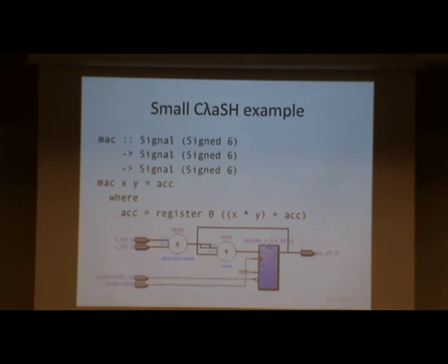The thing is that CLaSH will not infer the sequential hardware for you. You have to write down explicitly where you want to put your registers. There are other languages that derive this. I think this gives you a cost model or operational semantics that's easy to read about: how large your circuit is going to be, where the registers are, and things like that.